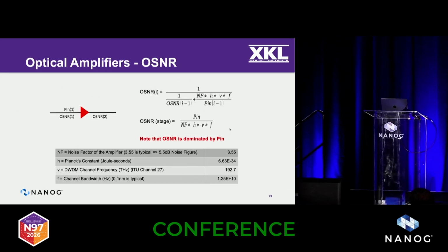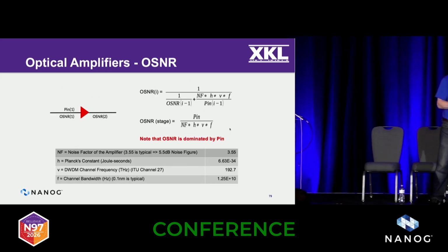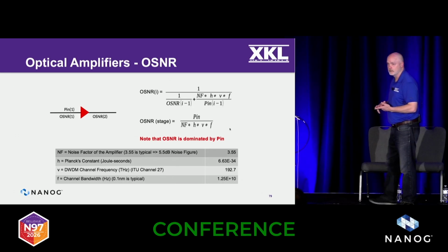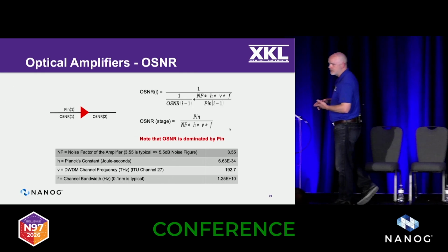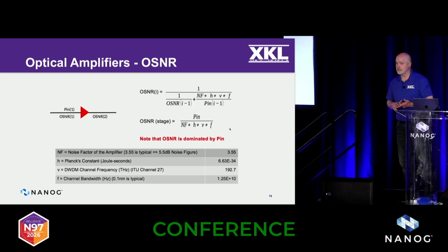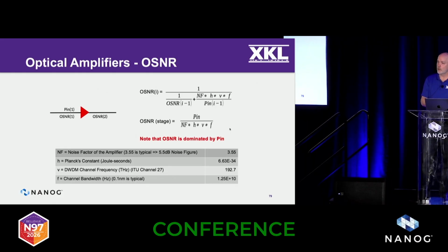We just did a 250 kilometer link with a customer. That's a long ways, 250 kilometers. We've got to have Ramans. We've got to have EDFAs. We might have to dial the data rate down. So this is where that 400 gig signal I was talking about, yesterday's technology running a modulation scheme of QAM16, that OSNR requirement is much, much higher than running at QPSK.